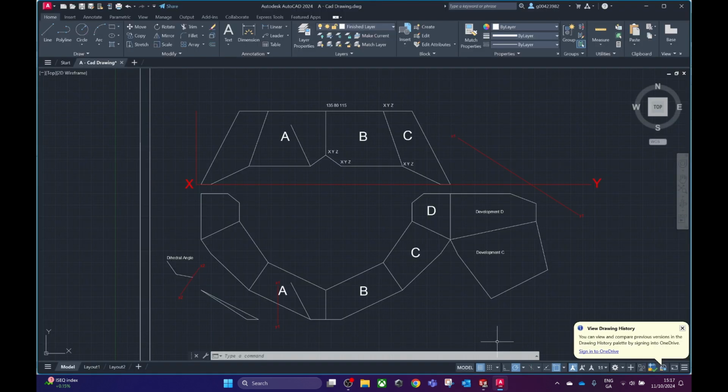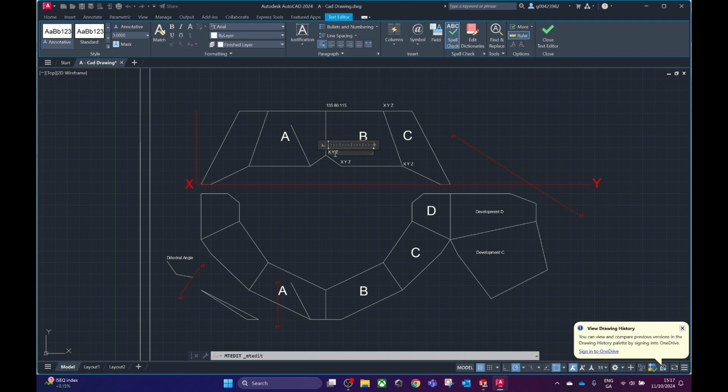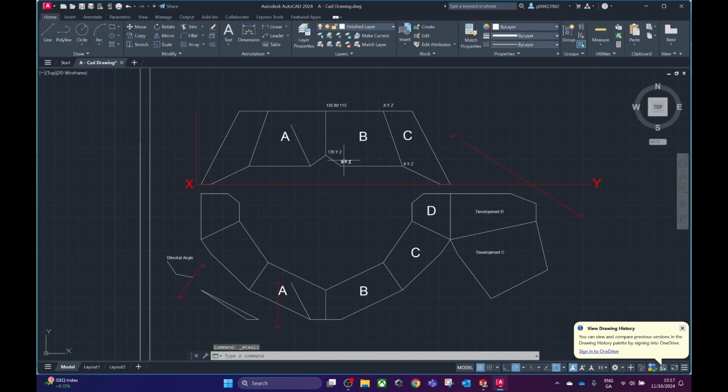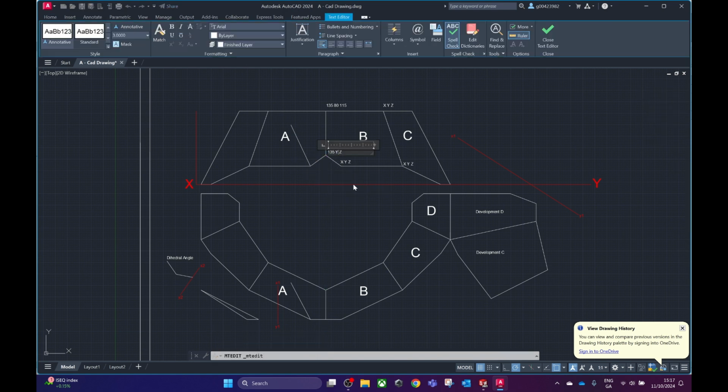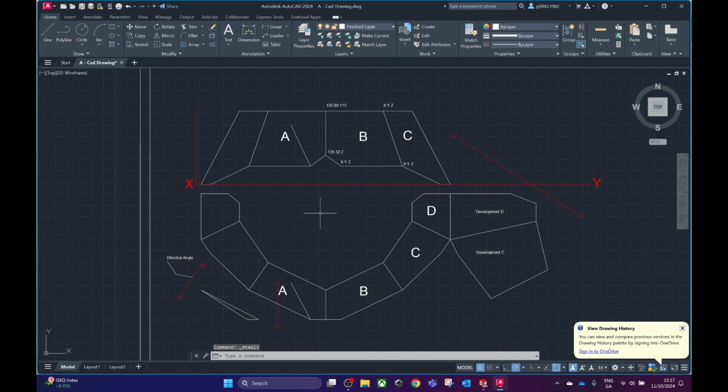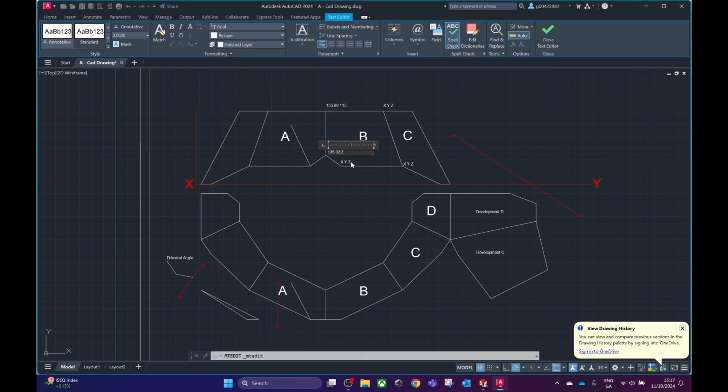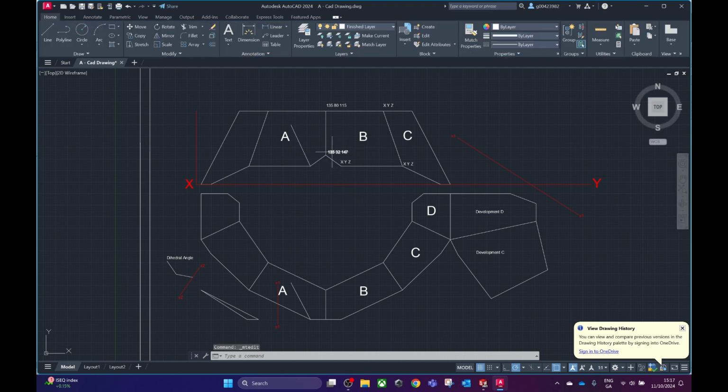So now what we're going to do is get this point here, and then when we get this point, we'll have this full line drawn in. So the same thing goes again. Let's get our X coordinate. That is going to be 135. So let's edit that, 135. Our Y coordinate is going to be from this point down to the XY line, which is 32. And let's get our Z coordinate, which is going to be down here, bring it up to the XY line, which is 147. So let's edit that to be 147.